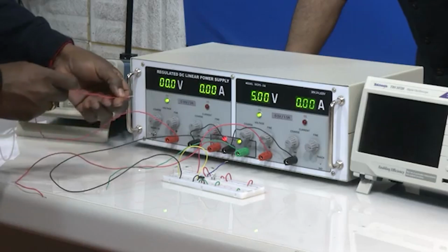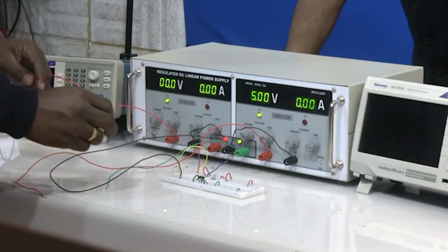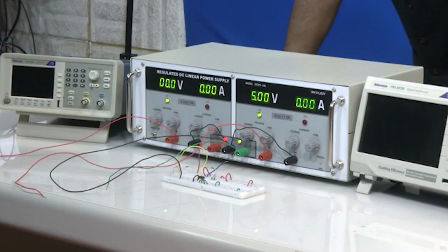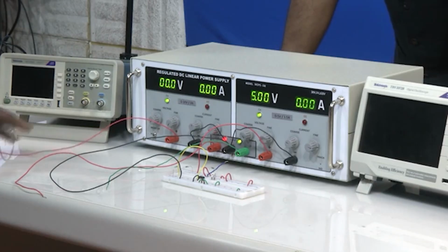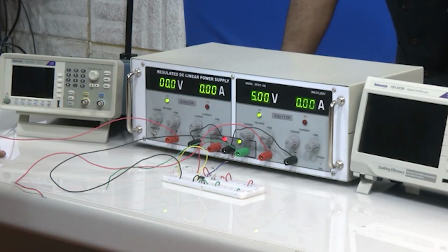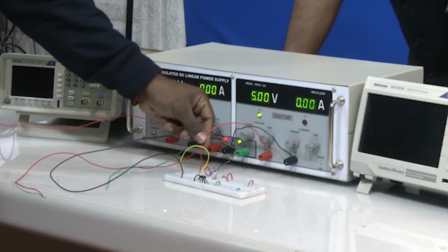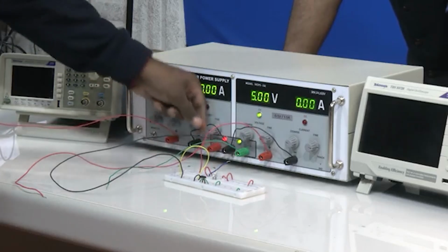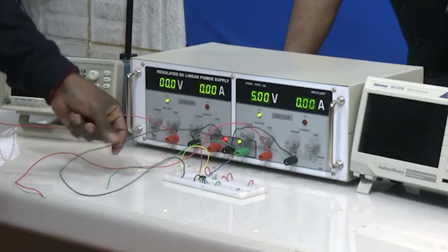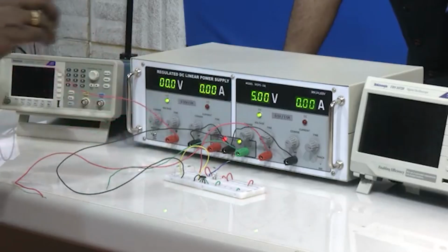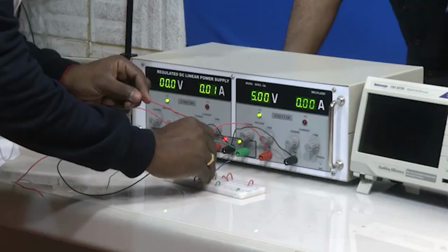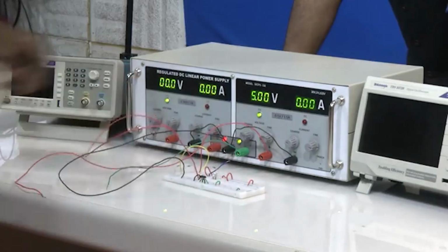Now, in this case I am sorry, since our circuit required plus 5 volts and 0 volts, that is why we are applying plus 5 and 0, not plus 15 and minus 15 for this particular circuit of comparator. Now, we have connected plus 5 volts to plus VCC, as you can see on the DC power supply, and ground to the minus VCC, alright. Now, we will apply voltage to the non inverting terminal of the op amp, alright.